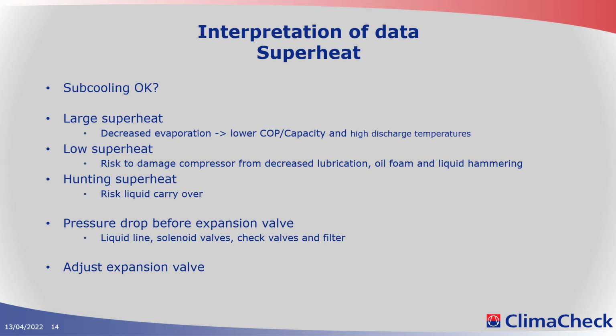We are going to have the biggest risk of hunting of the expansion valve when we have a very high pressure ratio and low capacity.